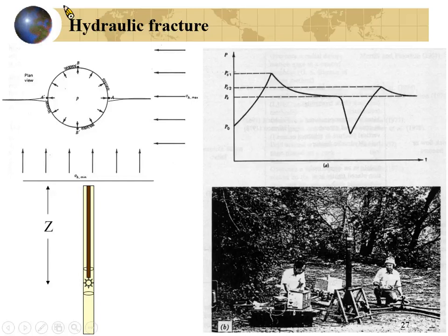The sigma theta here is maximum. After this location, the sigma theta will become smaller and smaller, and finally it will go into a steady state. Correct? So here, you will overcome the sigma theta at the tunnel wall. After this, the required pressure to make the fracture open will become less and less, so it will decrease and go into a steady state.